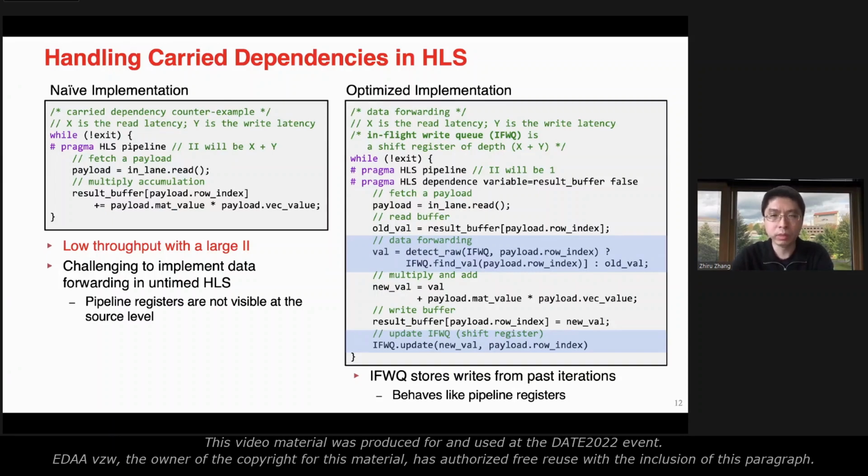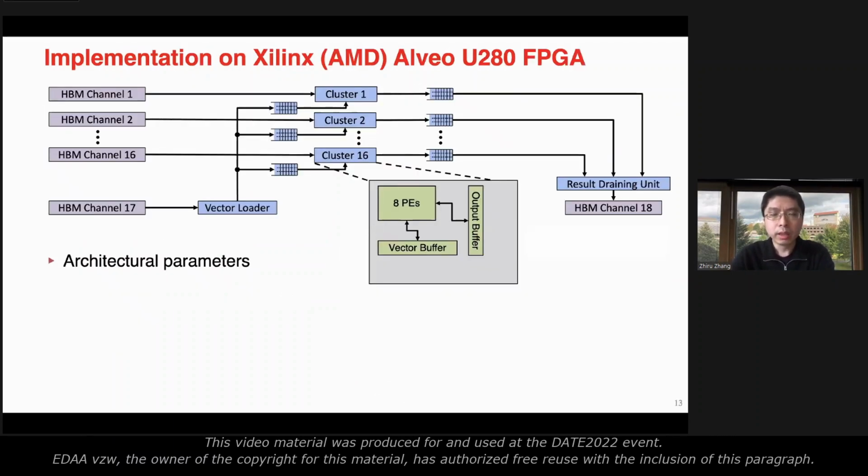This actually provides some good templates, because these days there are many good HLS code templates for handling sparse workloads, dense workloads like matrix multiplication, how to do systolic arrays, how to do line buffers or window buffers for stencil processing and such, right? But there are actually not many useful templates for handling this kind of sparse processing.